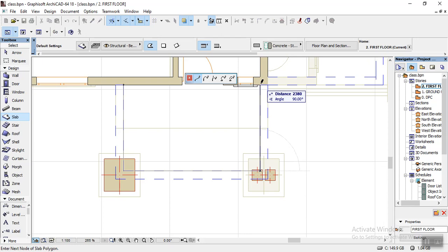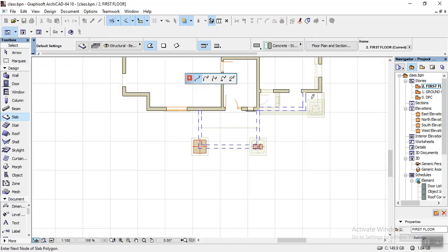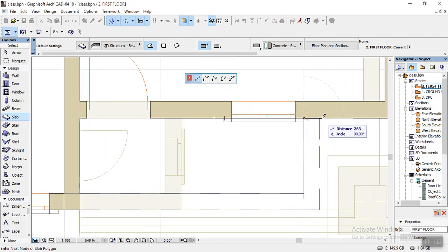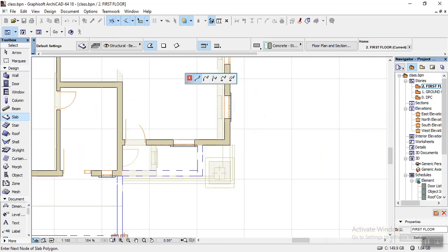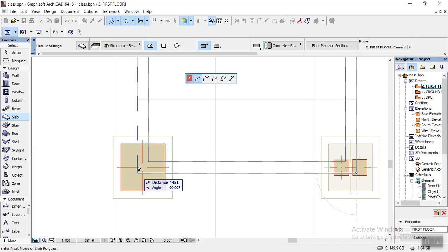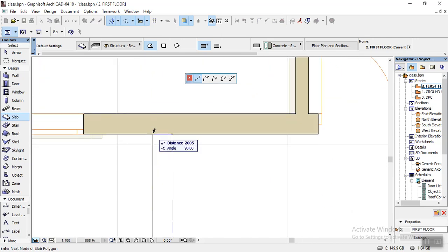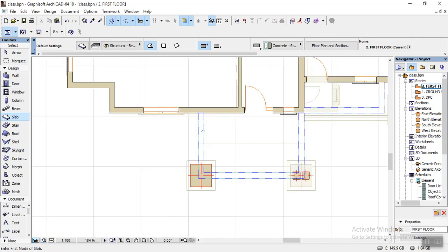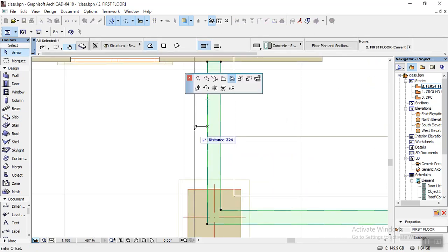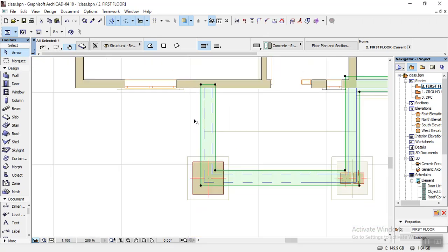You pick this edge here. Always follow what I'm doing. You pick this, then you come down to this spot. We're going to offset later. Let's just get it done first. You come down here. I don't want to use different slab tools. I just want to use one same slab, then I'll offset them differently. I'll come down here. This being done, there is a slab here now, so I'm going to offset this to 100 millimeter.